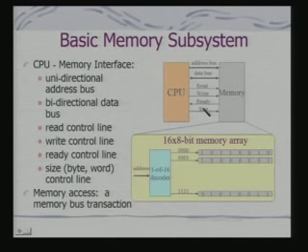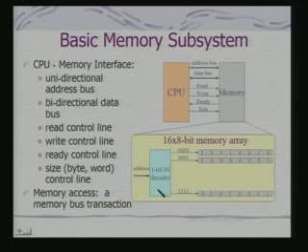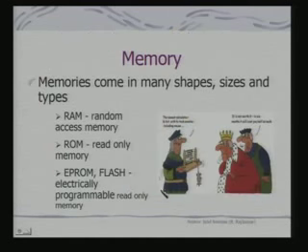The size indicates the number of bytes that are expected to be transferred through one read or write cycle. So effectively, a memory access, what we call, is a bus transaction. And the nature of the bus transaction can in many cases be defined by a finite state machine. So here we are showing how this decoding can take place. There will be an address, it will be decoded, and individual words in the memory will be selected.